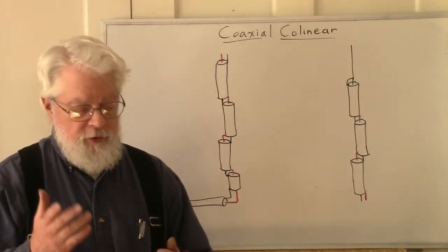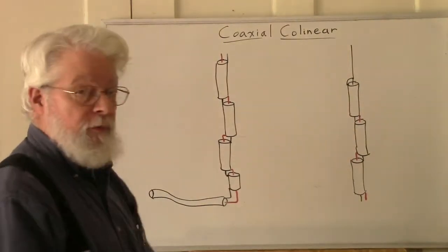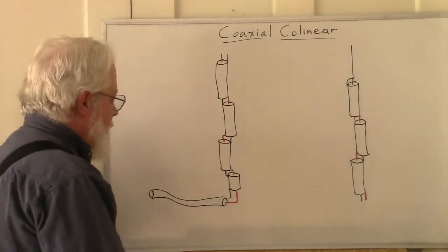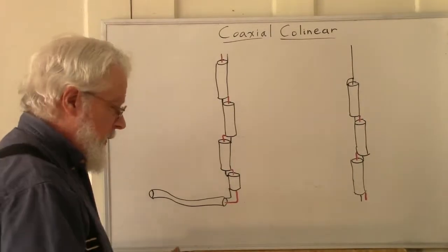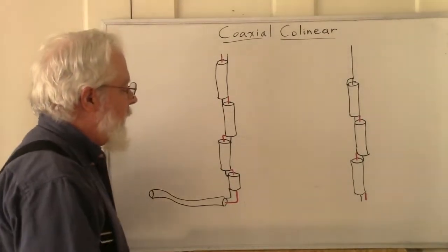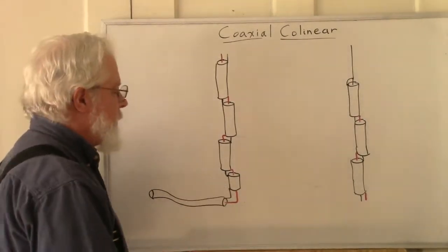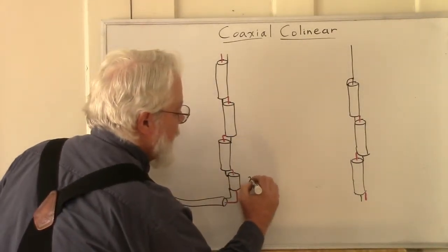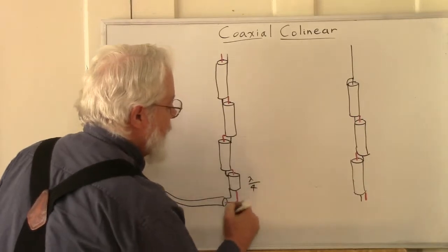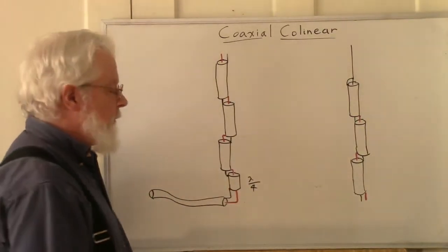It's a good antenna. So here's how it works. It's really, I think, kind of slick. We have a feed line of any length, 50 ohm feed line, doesn't matter what length it is. And the first thing we come into is a quarter wave matching section. So here's our little lambda over 4, a little quarter wave section right there.